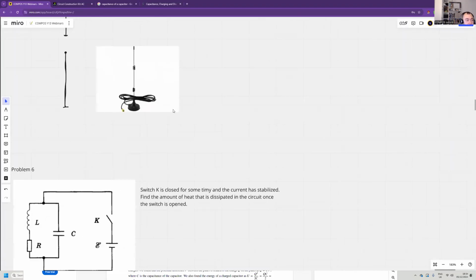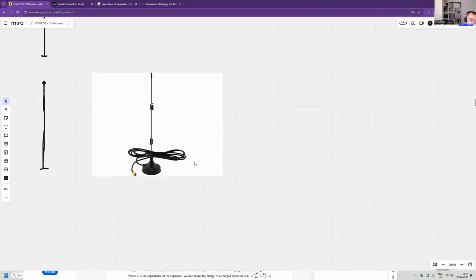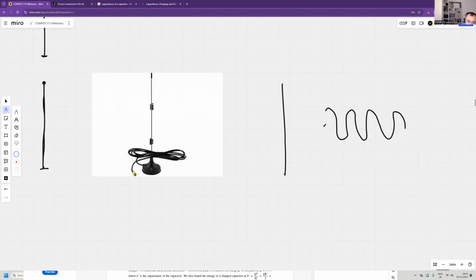If you want to receive a signal and the incoming electric field is horizontal, it will not produce oscillations in the antenna. So how does a receiver work? You have an antenna and there's an incoming transmitted wave, and if this wave is vertically polarized, that means that the electric field is vertical.